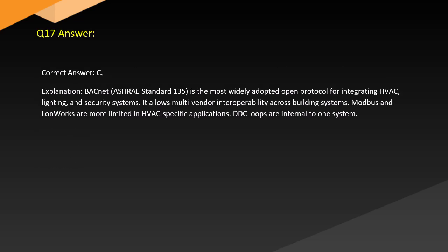Answer. Correct answer: C. Explanation. BACnet, ASHRAE Standard 135, is the most widely adopted open protocol for integrating HVAC, lighting, and security systems. It allows multi-vendor interoperability across building systems. Modbus and LonWorks are more limited in HVAC-specific applications. DDC loops are internal to one system.